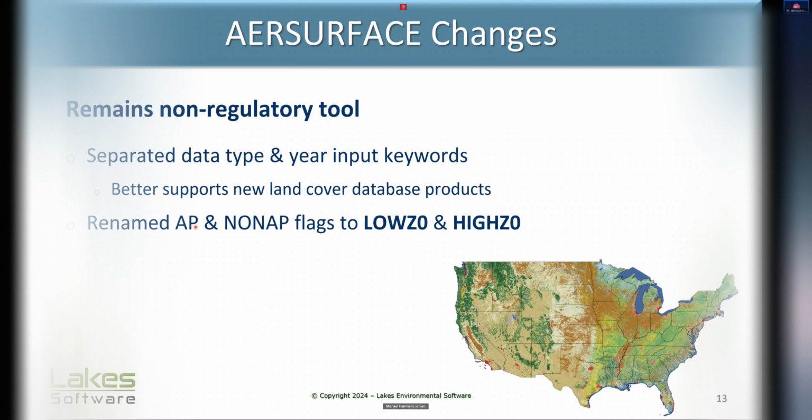You have runways and tarmacs that are impervious in nature, but they don't have the height associated with an urban developed boundary layer. They're very flat. And so by indicating low Z0, you can properly indicate that the land use is not as high in height, but still represents some sort of development.